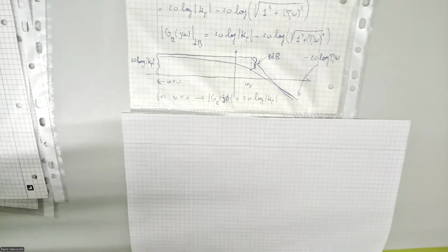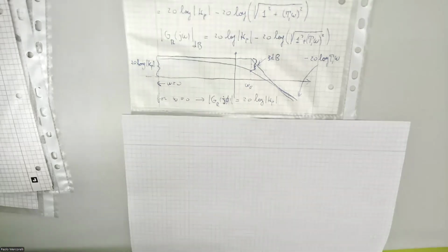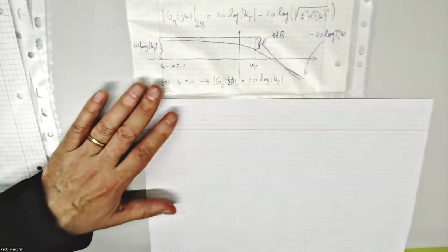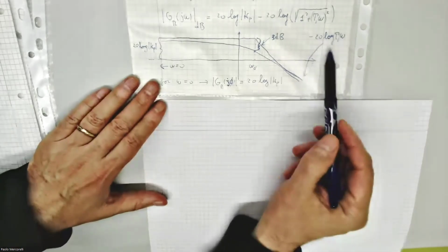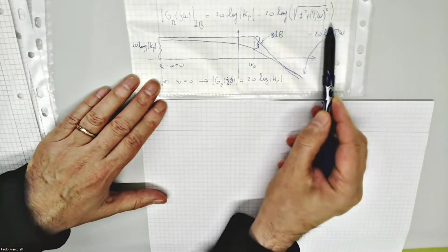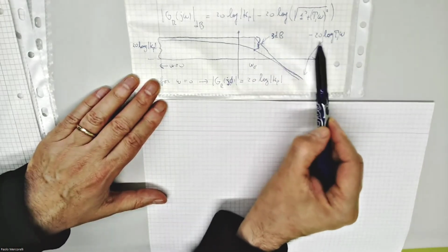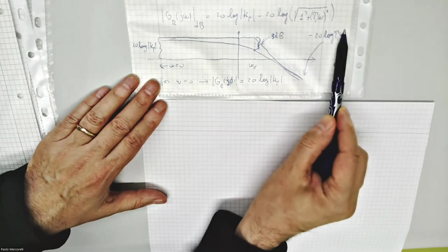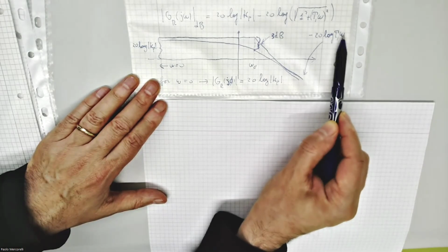I don't know if I have the calculation of omega e here. It could be that you have it in the slide. Yeah, but it's not difficult. It's an exercise I show you from math. Basically, when this element here equals Kp. This means omega Kp equals Kp divided by T1.